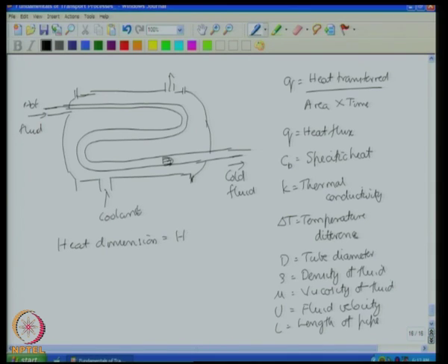So, this makes it clear that there is a separation between the thermal properties and the mechanical properties in this system. The thermal properties are different from the mechanical properties, because the thermal properties involve the transfer of heat energy, whereas the mechanical properties only involve mechanical energy, and the two are different. So, once I have that, then the number of dimensions that I have is heat energy, mass, length, time, and temperature theta.